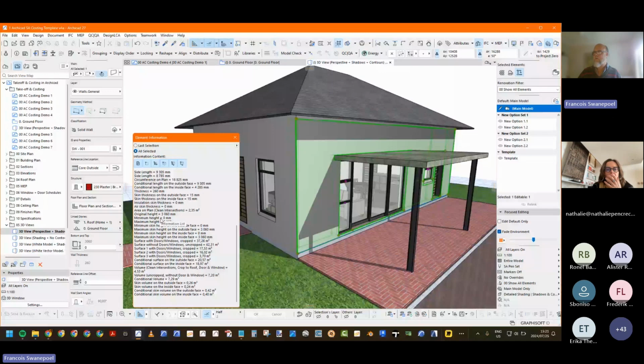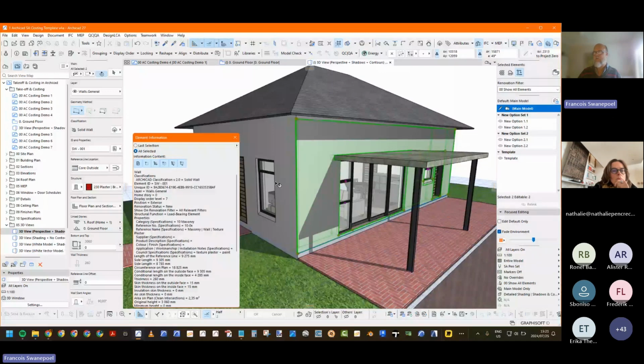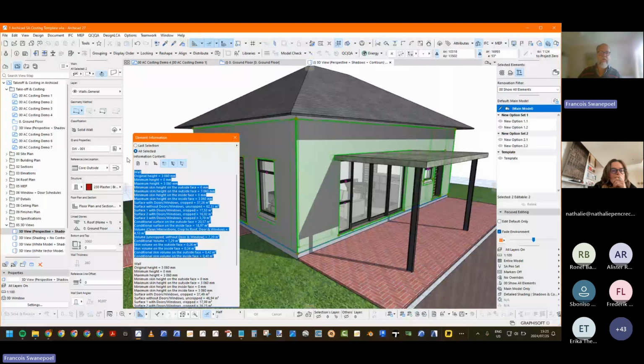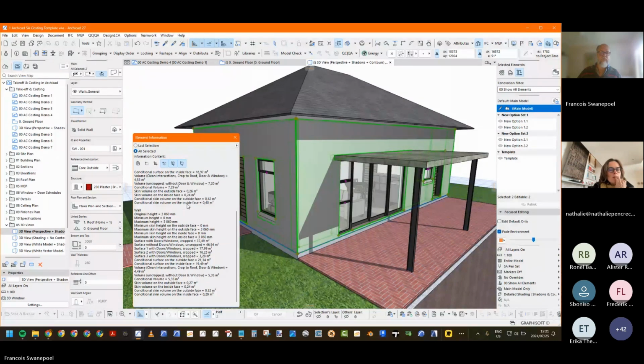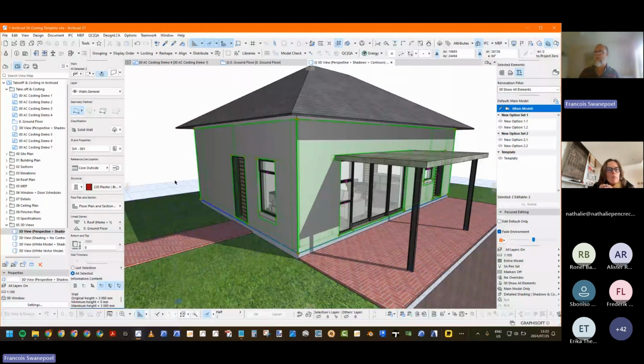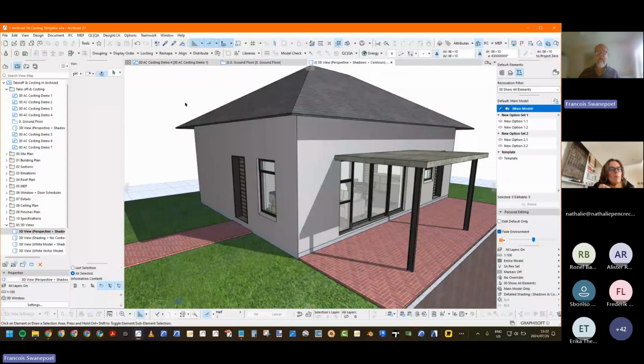And if you select more elements, let's just go to this collection here, you'll see that it gives you the details of one wall and then the similar information from another wall separately, nicely grouped. So these are the quantities and values, parameter values that we can take and use in quantity takeoff and calculations in the schedules. I'm just going to park this there. And now you know the basics of where these quantities are coming from. It's already in there.